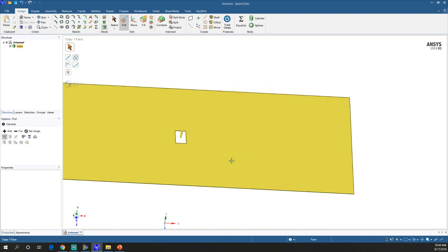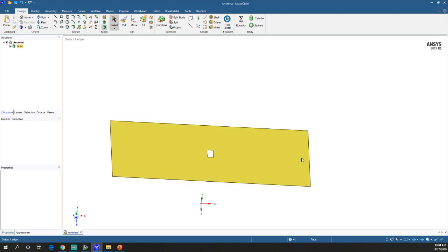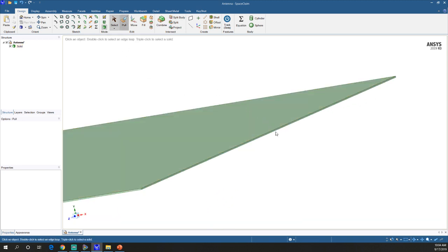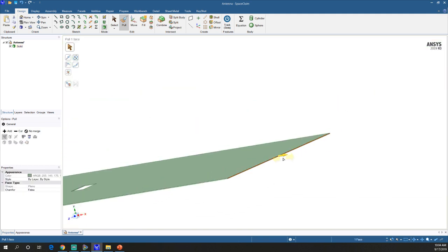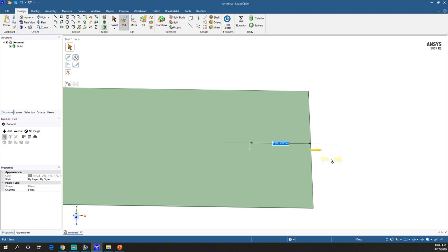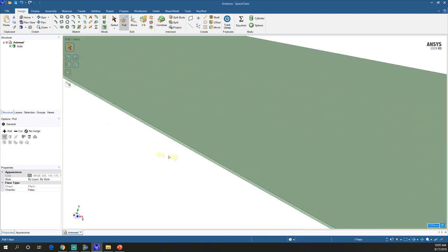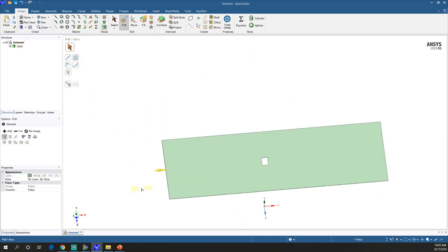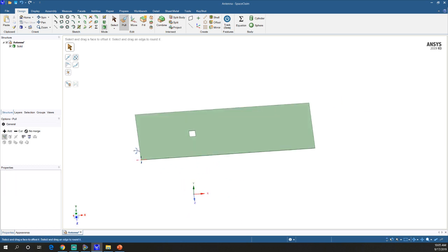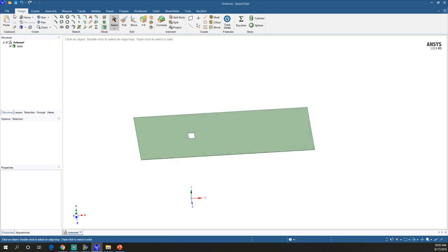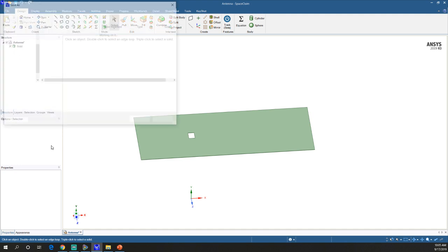Typically for wind loading, the wake region is kind of interesting. You can imagine flow coming in here, and there's not much going on upstream. But as soon as the flow hits our object and starts to flow downstream, there are vortices, there's a wake region, and that's usually fairly long. So we probably want to make our wake a little bit further, another meter, let's say. In comparison, our upstream doesn't need to be quite this long, so we can just drag it in to keep the simulation small. So this is what we need to do our analysis. I'm going to save this.